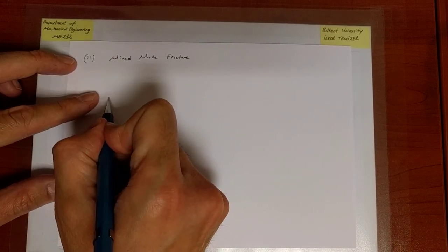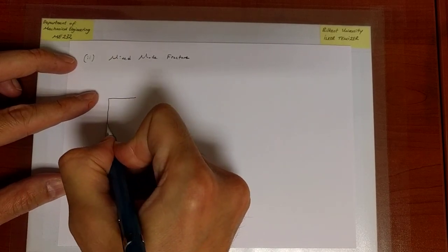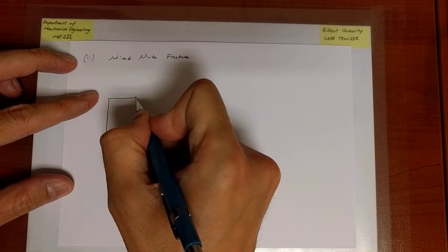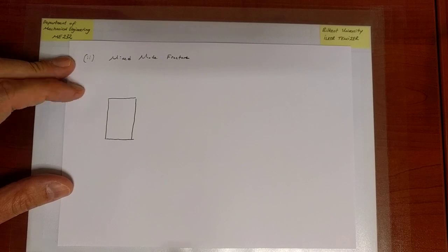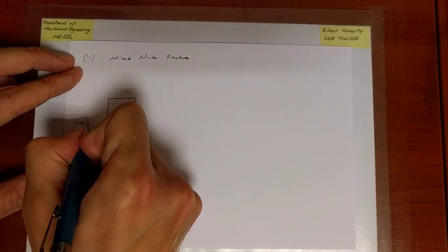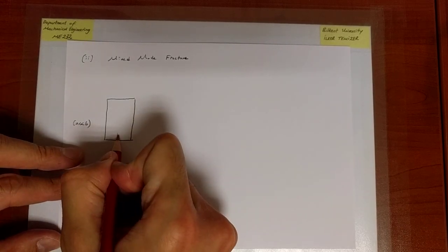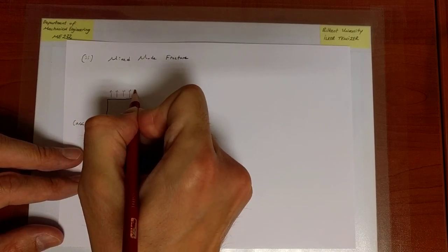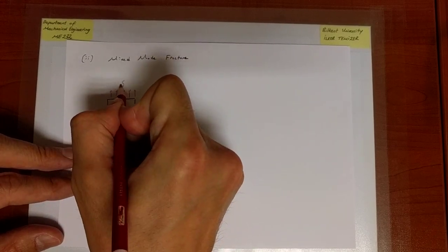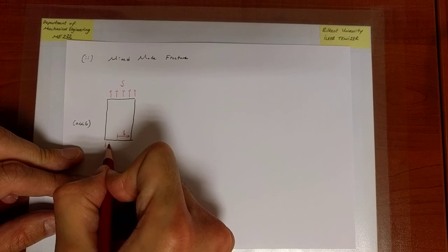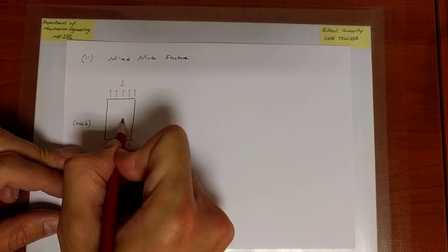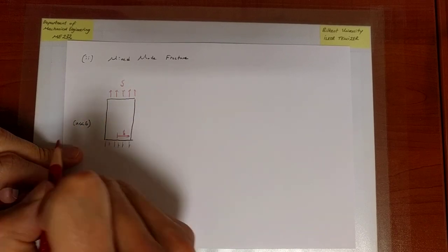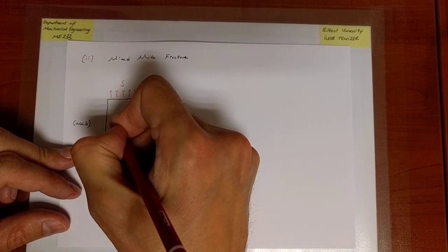Okay, so to demonstrate this idea, we will again take our usual plate, but although the plate example is very easy, we can just as easily enrich it beyond our existing level of proficiency. I'm going to assume that there is a crack, and that crack is much less than the half width. Looks like a standard scenario. There is a far field loading. The height, if you like, is very large compared to the width. Let's just denote it simply by S, of course, on both sides. So far, so good. If I put the crack like this, there is nothing fancy. It's our prototypical scenario, but I'm not going to put it like that. I'm going to put it at an angle.